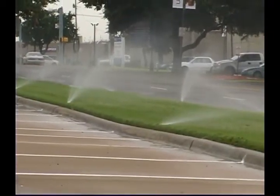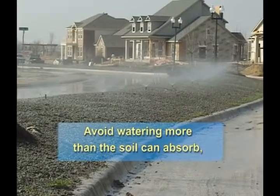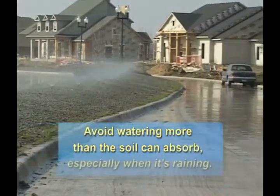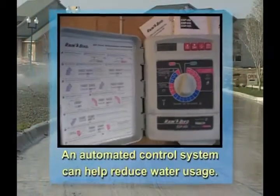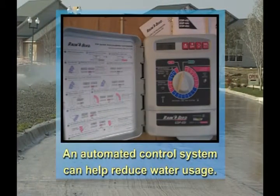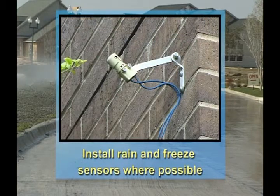Monitor rainfall and turn off sprinklers during rainy weather. Avoid watering more than the soil can absorb, especially when it's raining. An automated control system can help reduce water usage. Install rain and freeze sensors on automated systems where possible.